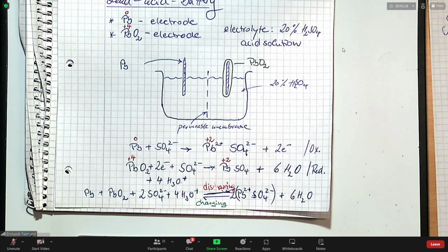And so you can operate a generator, the alternator, which is producing electrical power for charging the battery. And you also need some electrical power for the light, for your radio system, for your window cleaner, whatever, operating with electrical power that's produced as a byproduct of the rotation in the engine, and you use it in a generator to produce electrical power. But it's always stored intermediately in the battery and used out of the battery.